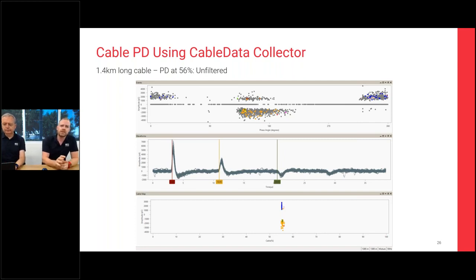What we're talking about here is your unfiltered data. There are two high pass filters that we apply to the data, which help us, A, detect if there's PD occurring, and B, get rid of noise. As I said earlier, usually there's a lot of electromagnetic noise on all our high voltage cables out there, because your system's connected to everything and signals are bouncing off everything. So we use the filters to see through the noise so we can see PD. But the higher the filter you apply, the less distance down the cable you can see. So we use that information to our advantage as well.